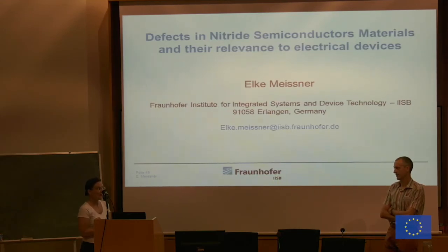The aluminum nitride grown as a larger crystal has a different possibility due to the PVT process. And the PVT process is easier to control than a chemically mediated process like the HVPE growth. So the PVT growth process can produce better quality, and it does produce aluminum nitride crystals with a good quality and a decent size.